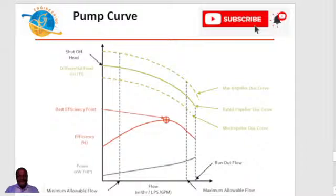Alright, so you can see that differential head is somehow inversely proportional, for any pump, to the flow rate. As the flow rate or the pump capacity increases, the differential head reduces. In the same way, as your pump capacity or pump flow rate reduces, your differential head, or total head requirement, also goes higher.